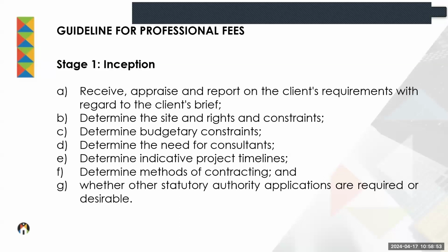Are there restrictions placed on certain things in terms of a guideline of an estate, or there might even be restrictions placed in a town planning scheme on what we cannot do? Let's look at building lines. Are we going to keep within the building lines? Do we know the time constraints imposed by the SPLUMA regulations by local authorities, where it comes to building line relaxations, where it comes to rezoning applications?